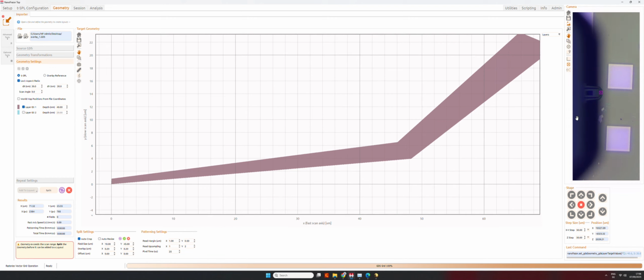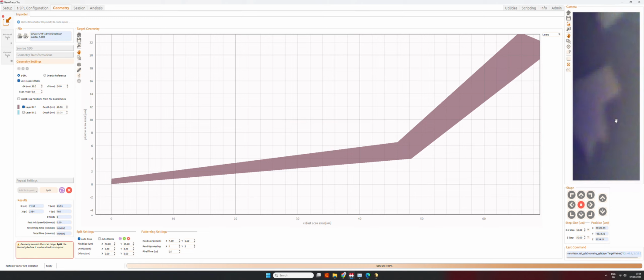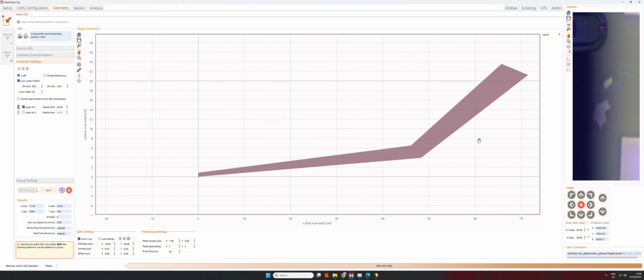My best suggestion to you when doing overlay on pre-existing topographies is to pattern without a feedback, because usually the feedback struggles a little bit when patterning across this change in the height of the topography. So here we are around a 30 nanometer step, so it's a little bit harder for the feedback to follow this topography at the moment.